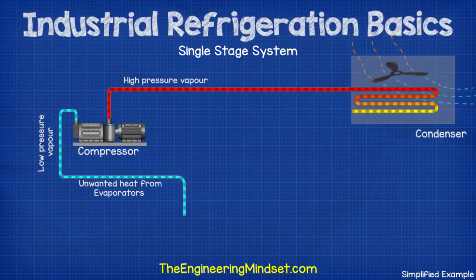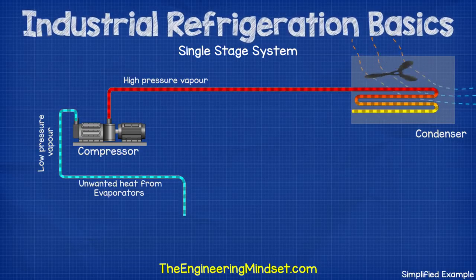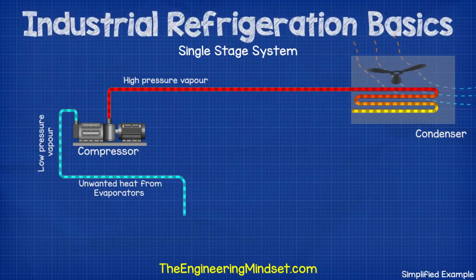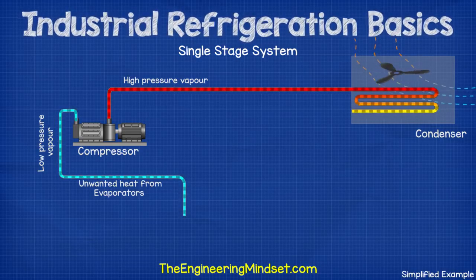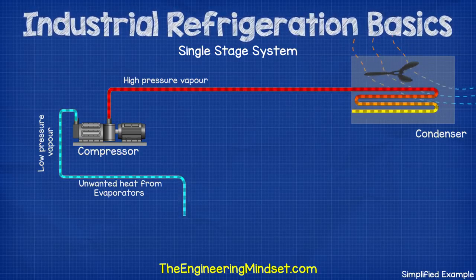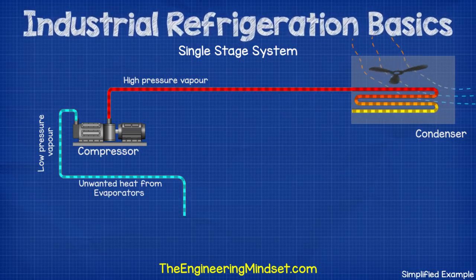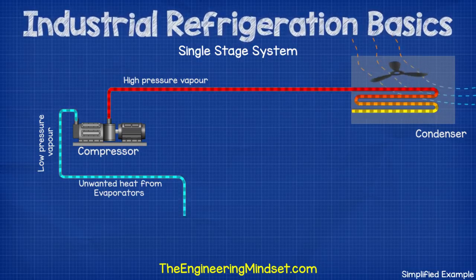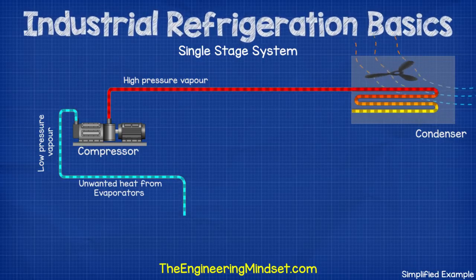The condenser cools the refrigerant down by pulling the unwanted heat out of the refrigerant and discharging this heat into the ambient outside air. This is typically done by passing the hot refrigerant through the inside of some small tubes and using a fan to force the cooler ambient air across the outside of the tubes to cool it down and carry the heat away.